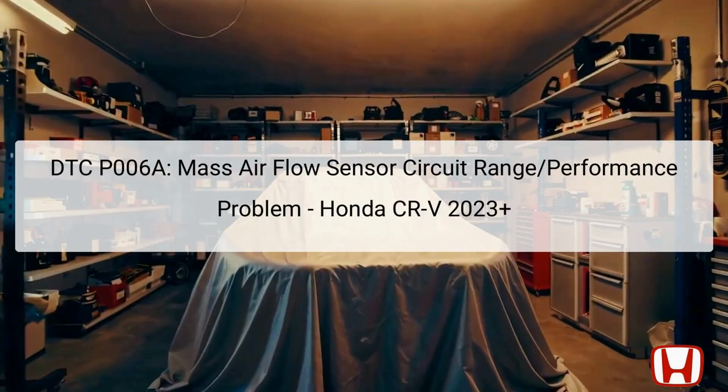This presentation focuses on DTC P006A, which stands for Mass Airflow, MAF, Sensor Circuit Range Performance Problem, specifically for the 2023 Honda CR-V. This error code indicates an issue with the correlation between the intake air measured through the MAF sensor and the intake air assumed by the manifold absolute pressure MAP sensor. In essence, if the data from these two sensors does not align within set parameters, the Powertrain Control Module (PCM) registers this discrepancy, triggering the DTC.